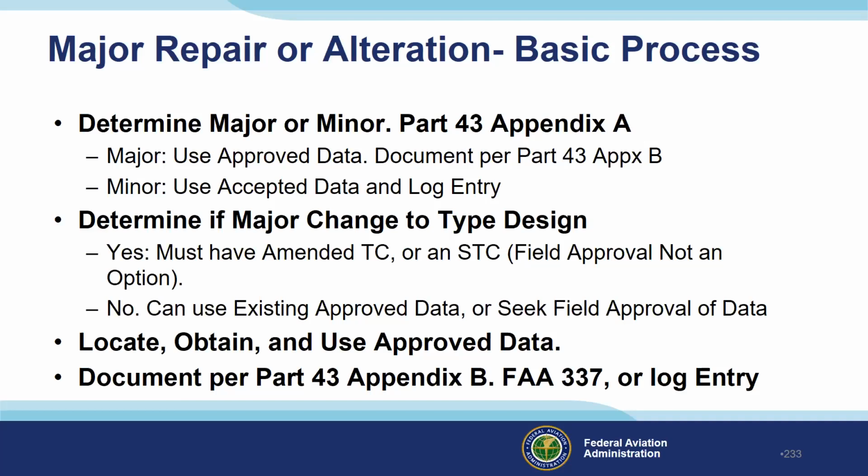If you determine it's a major change to the type design, if the answer is yes, then you must have an amended type certificate or an STC, supplemental type certificate. A field approval is not an option if it's a major change to type design.